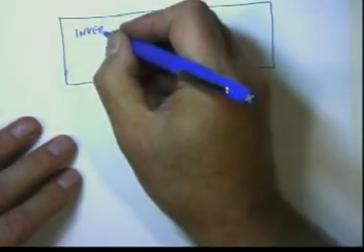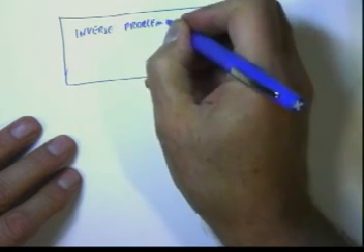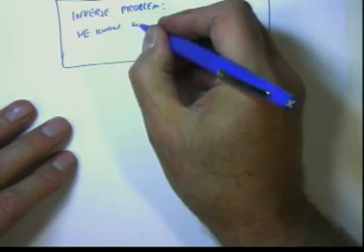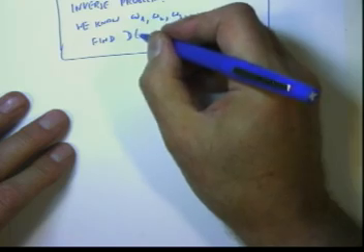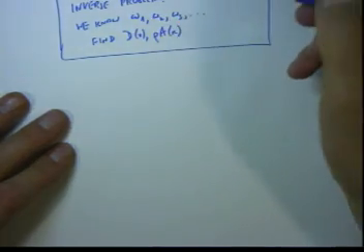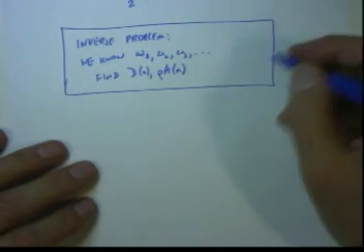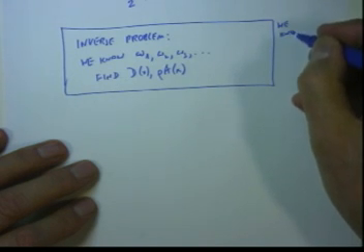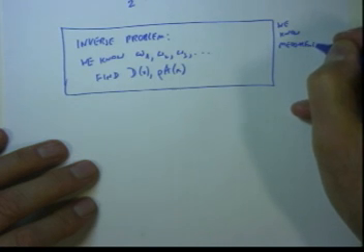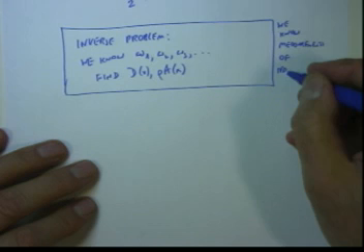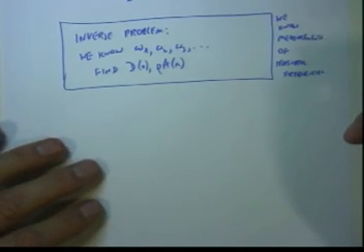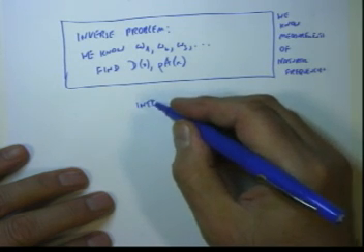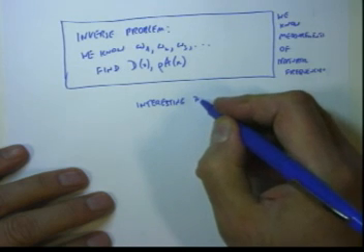Just before that, what would be the inverse problem? Inverse problem is like this. We know omega 1, omega 2, omega 3, etc. Find D(x) and rho A(x). That is an inverse problem. So that means that we know measurements of natural frequencies. So there is a very interesting theoretical result.